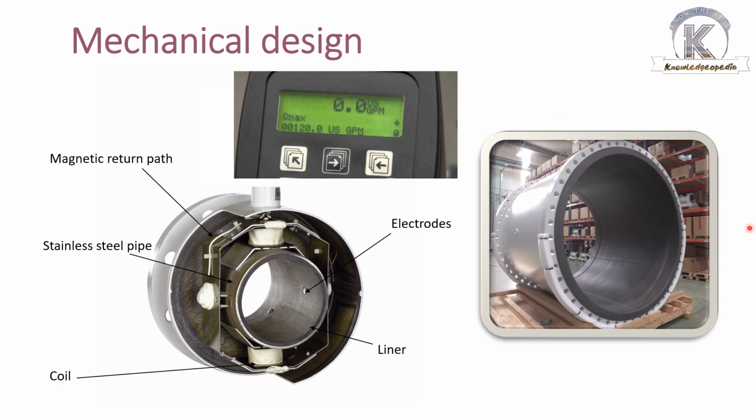The magmeter also has an excellent turndown ratio. That means the ability to accurately measure flow from 0.1 meter per second to 10 meter per second, meaning a magmeter can be appropriately sized for the vast majority of applications found in the process markets. Magmeters are available on the market from 2 millimeter of nominal diameter up to 4 meter. A wide variety is available. It's a huge turndown, you can say.